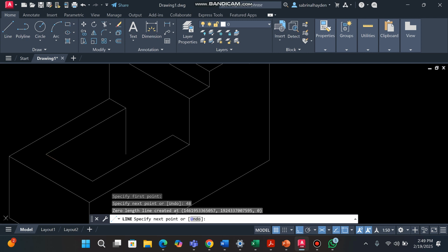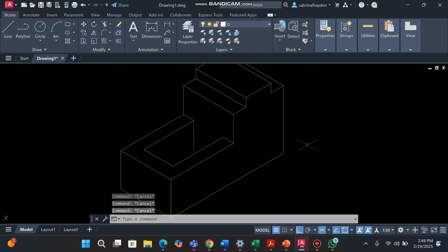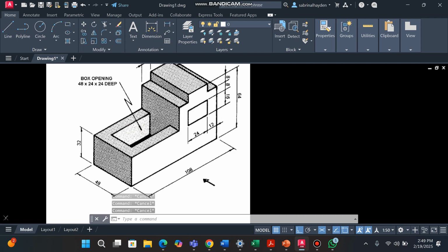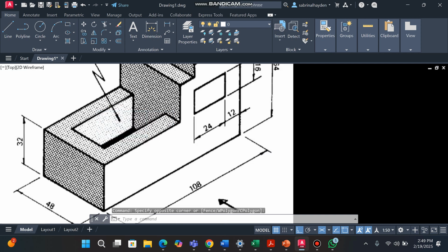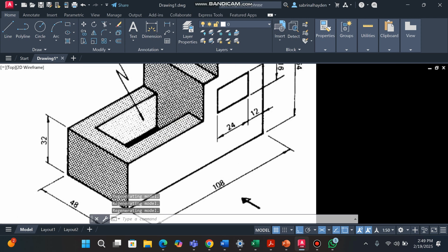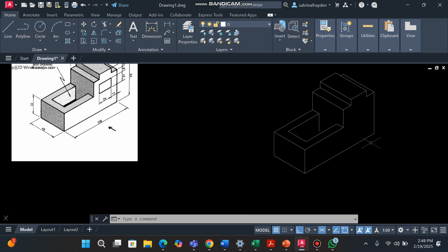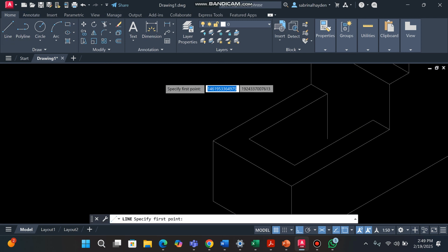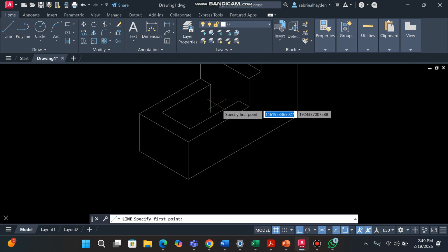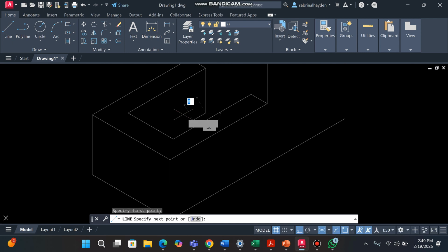So connected. Right. Now, if you realize, we have the face right here, the top part. We need to get the opening, the part in the gutter, down in this part right here. We have some of that already, but we need to complete it. So we're going to select line, select this endpoint right here and pull it out.